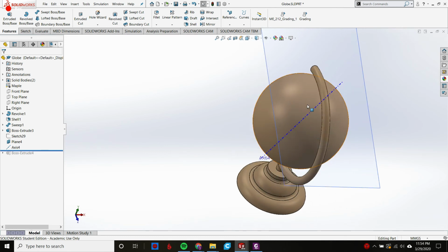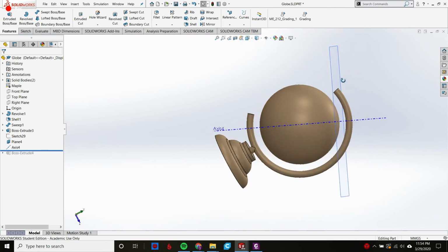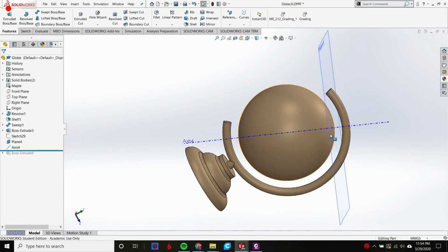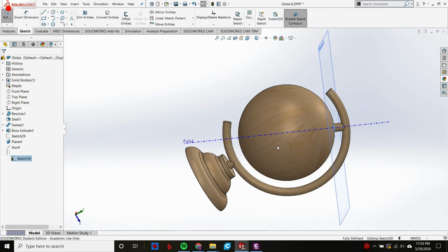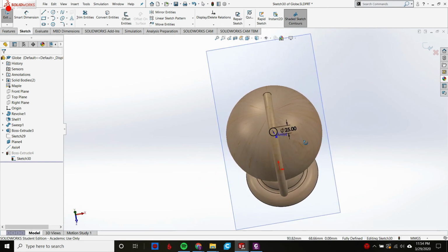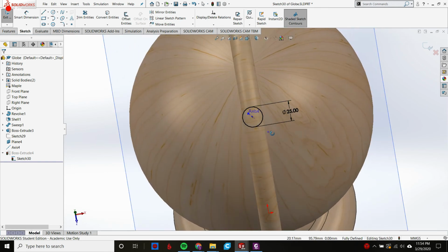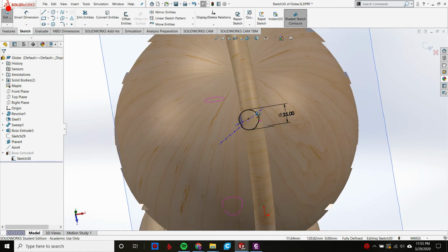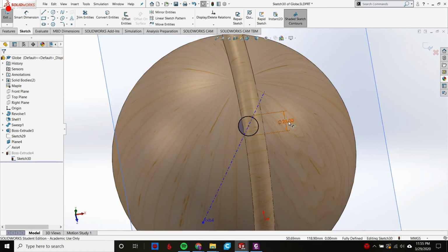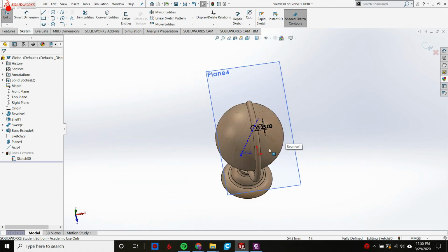So once we have this axis in, now we can just draw on this plane, because this plane is at the right degrees, since we measured that all out, and now the axis is turned into it. So our last little extrude is coming in here, right? And we draw a circle. We set that to be on that axis. The axis runs through the center of it. Again, it's 25 because we have that 25 typical.